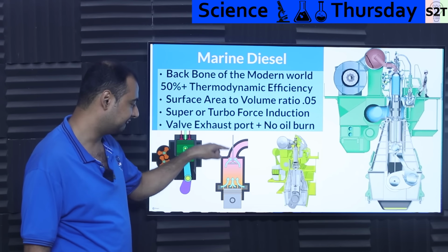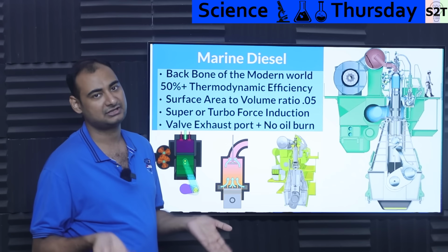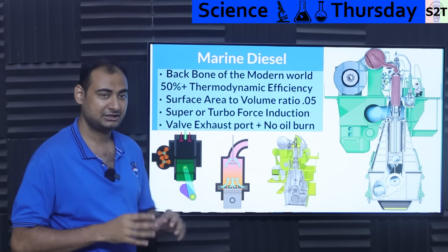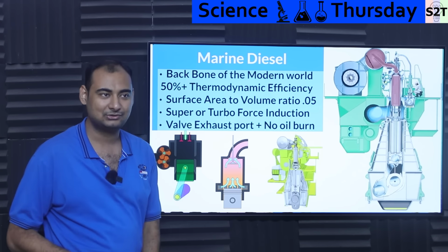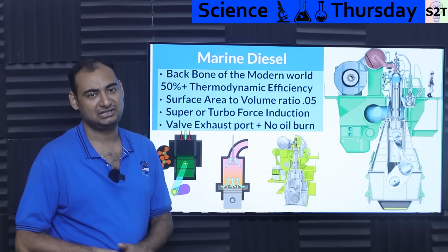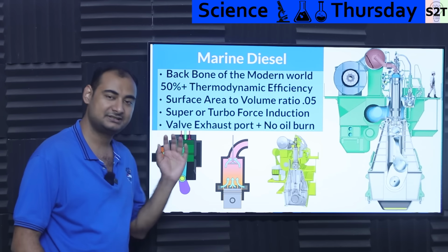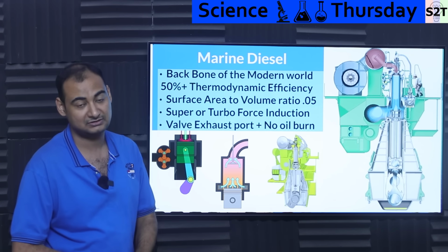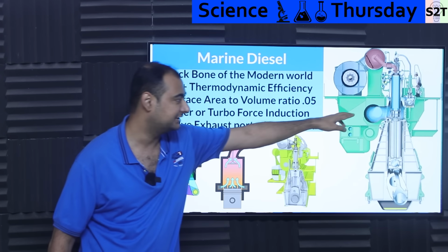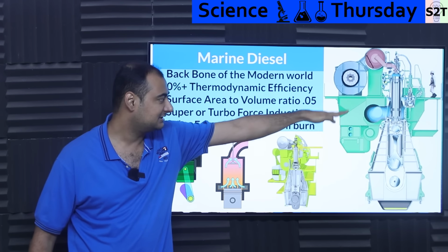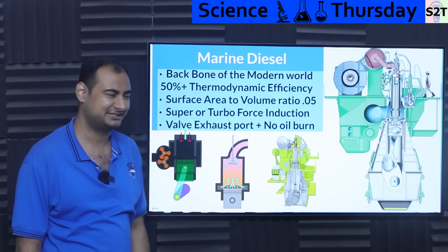Only one valve system, one valve, and you have complete uniflow scavenging, very power dense, and again, low RPM means surface area to friction ratio is very low, very efficient, and again, they don't even have a gearbox. They directly yeet the propellers. Now, the penalty is because the RPM is so low, the pulses would be far apart. So they have a lot of cylinders, sometimes 12 cylinders, sometimes 16 cylinders. So this is the marine diesel, the most awesome use of two-stroke topology with just forced air breathing in. There is no natural aspiration. Although it can be done where instead of having the turbo, you can remove that part, seal the bottom part, have reed valves and have a port. It can be done. It's just not done because what's the point?